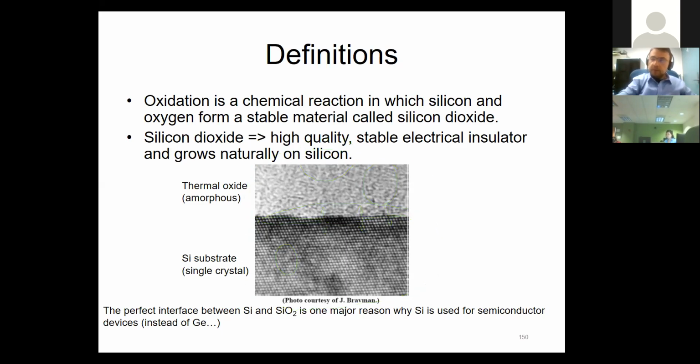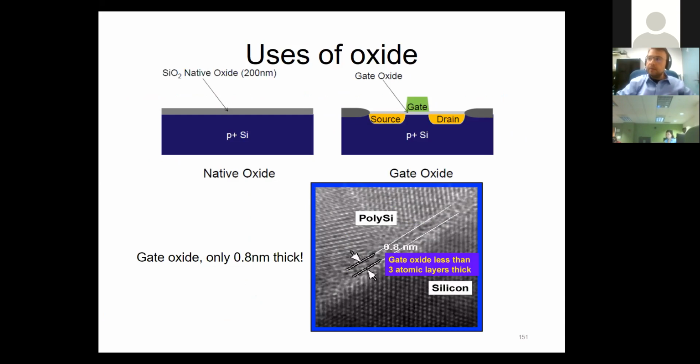All right, so why do we need an oxide layer? Because in the first place, silicon is nice. We can play with its conductivity. That's what I was trying to emphasize over these lectures. As a semiconductor, you can tune its properties by playing with temperature, by playing with dopant levels. All those are fine. But then when you build your devices, you like to also create an insulating layer too. You like to have some portions that will be isolating the other portions. For that reason, the oxide will be very, very handy.